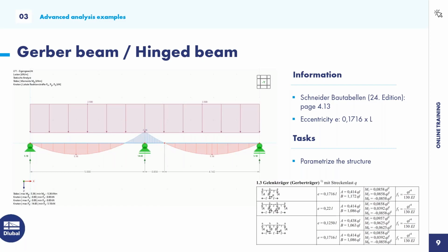And this is pretty useful for design of members because you can optimize your utilization of the beam throughout the length. So if you have the same design strength in hogging and sagging moments, this is quite convenient.